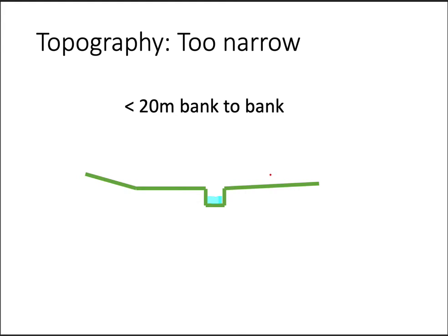All right. Another example, and I talked about this early in the beginning, we also have a minimum. And so this is pretty simple. Community members will have trouble crossing, but why don't we build less than 20 meters? The main reason is because you could build a much simpler structure. You could build, let's see, for example here, a simple truss bridge. That would be much more economical, much easier to build.